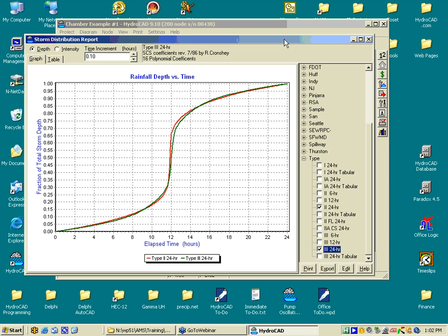Okay, and that's great, and also the choice there too is to do the rainfall. And Peter, I think you're showing some of how HydroCAD can deal with that question. Exactly. We've got an extensive rainfall library in HydroCAD that provides most of the local rainfall distributions that folks are using in specific jurisdictions, in addition to the standard NRCS or SCS distributions. And you can set those rainfall depths according to TP40 or other documents.